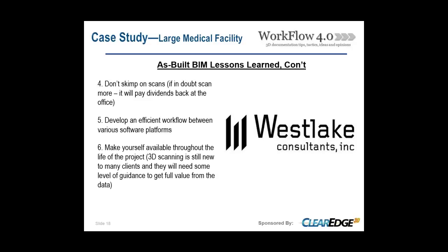Also, develop an efficient workflow between various software platforms. We're moving in and out of various point cloud processing programs and modeling programs: Edgewise, Rhino, AutoCAD, Cyclone, ReCap. Develop workflows. Each one of those tools has benefits and does something better than the others, but if you can't move in and out of them smoothly, you're going to struggle.